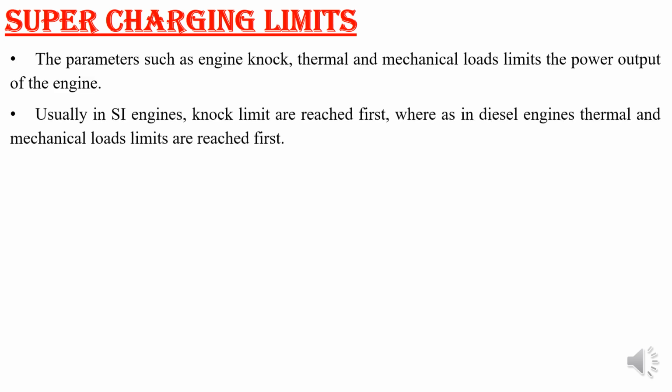See, now you know that we have to increase the pressure. How much should we increase the pressure? At what pressure can you limit this supercharging of the air? That we should know. Why do you have to limit? Because, as I have already told you, of knocking. Knocking will take place and it will reduce the engine life. Thermal loads will be there inside the engine, and the material has to withstand those thermal or mechanical loads. So, based upon these limits, that is the knock limit and thermal loads, we have the supercharger limit.